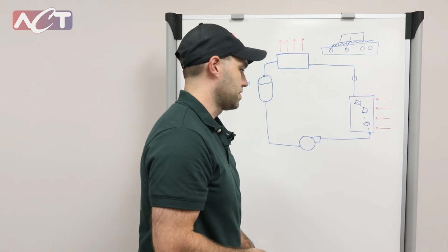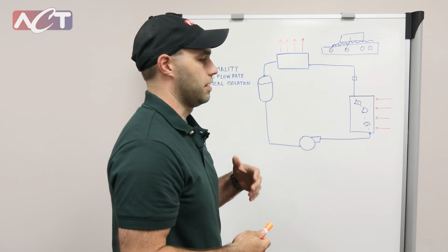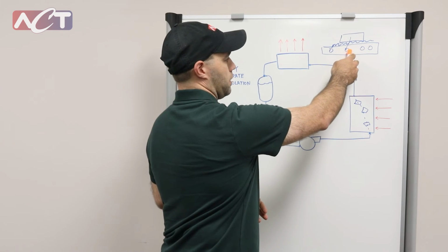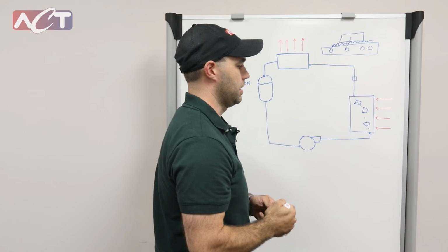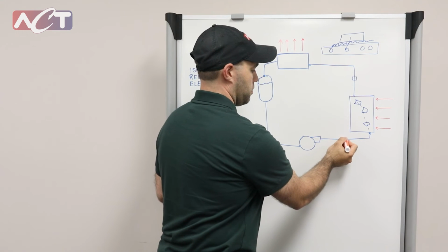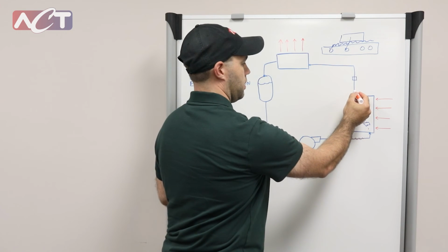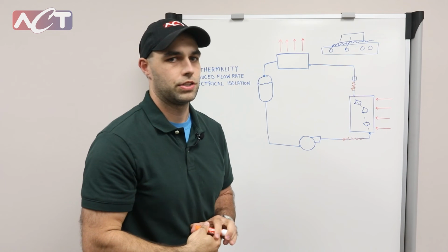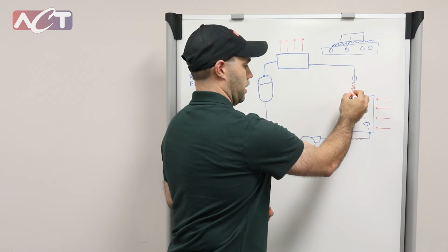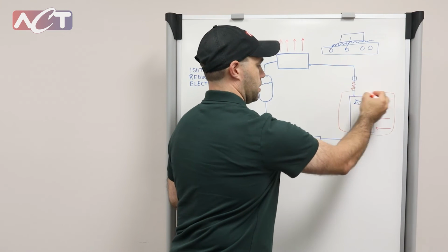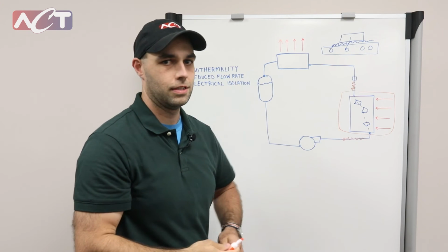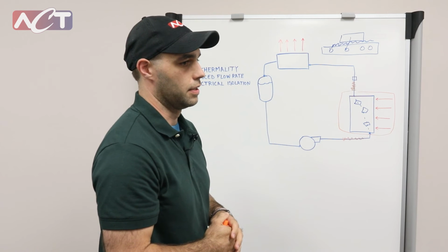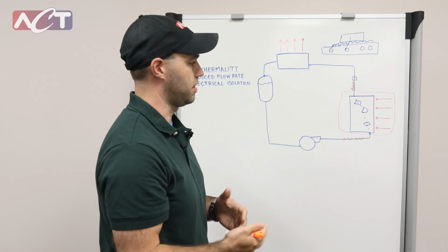So eliminating both those things in a pump two-phase system, you have the dielectric fluid, so you can not worry about the fluid itself conducting the electricity, and then these lines can be replaced with a non-conductive hose, which allows you then to just isolate this section completely, and that can be at whatever voltage, and the rest of the system can be at whatever voltage. And so you have that nice isolation.